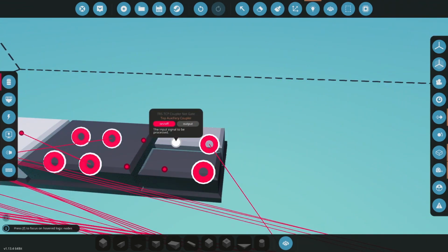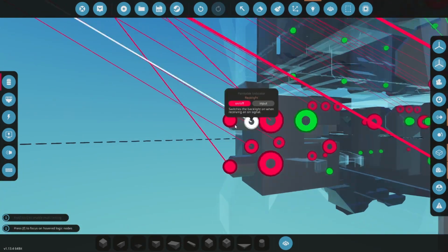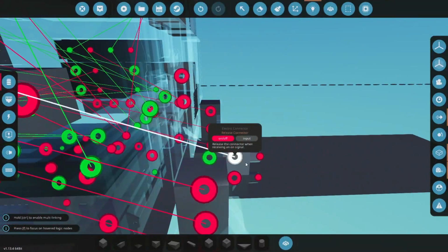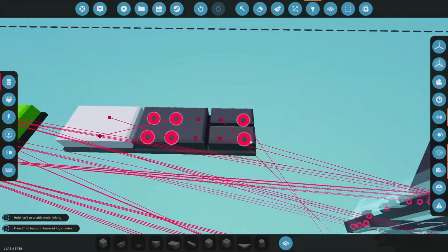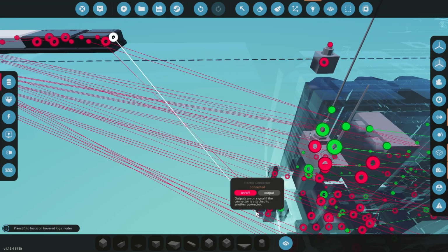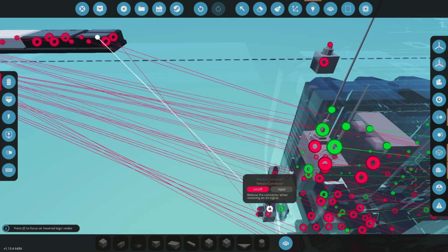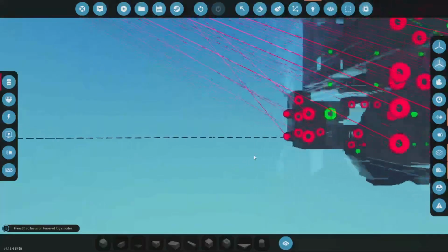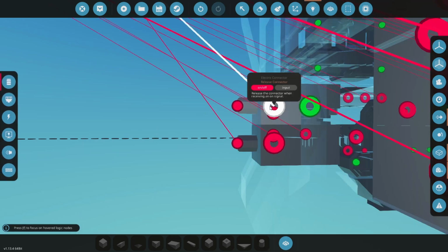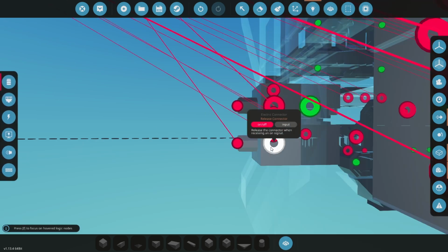And then the top auxiliary connector is the one that just does the electricity. And I connect one for the front and one for the back. So that's the top and that's the bottom. What this is doing is saying if this electrical connector is not connected, then release the other connector. That'll stop weird situations where this top connector tries to connect to the bottom connector of another wagon and gets all offset. So essentially this top one's always on release until this bottom one is connected.